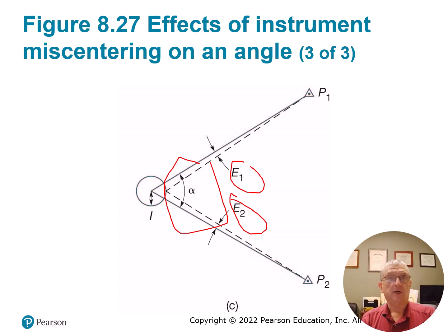And leaning on a tripod or touching it, it's very natural. I see students, just conducted another lab this afternoon, and students invariably put their hand on the tripod to help steady themselves, or because it just feels natural. But we're talking about micrometer readings, and if you move the instrument, or the instrument's out of level just a few seconds or a few minutes of arc, that transfers down the field towards what you're looking at. When you touch that instrument, you're moving it.